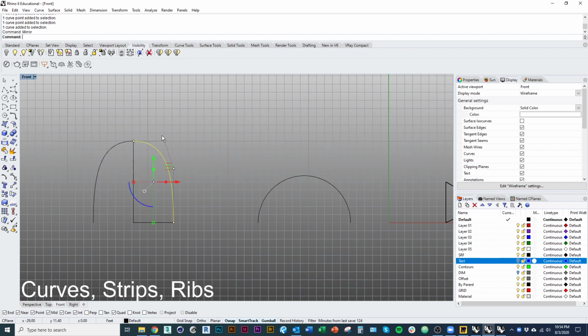And then I could mirror it like so, join it again. So that's a way to draw a less even arch type of curvature. And then the other type, or the other two types we might do are the parabola. For that, we know that's a specific type of curvature, and we can just type in the command parabola. And I think this guy works.